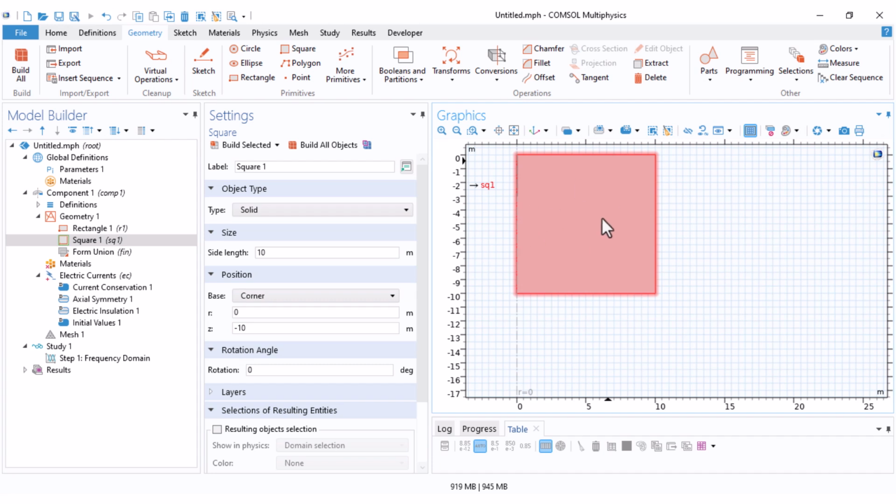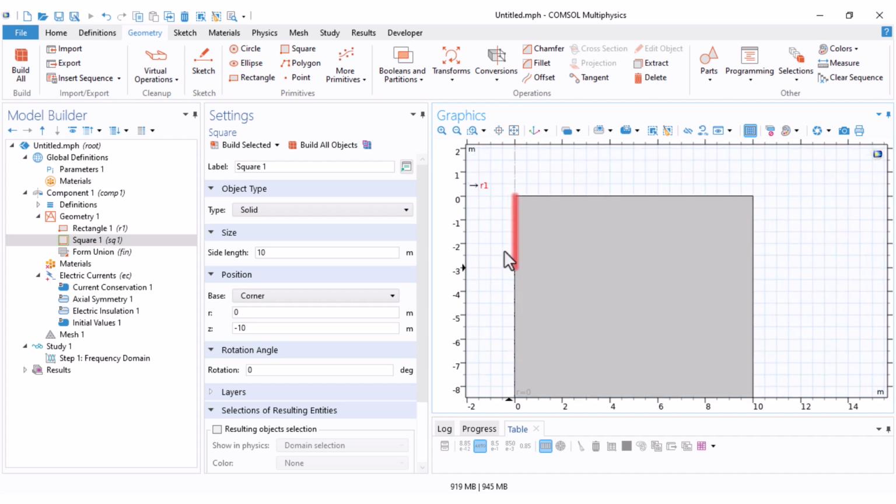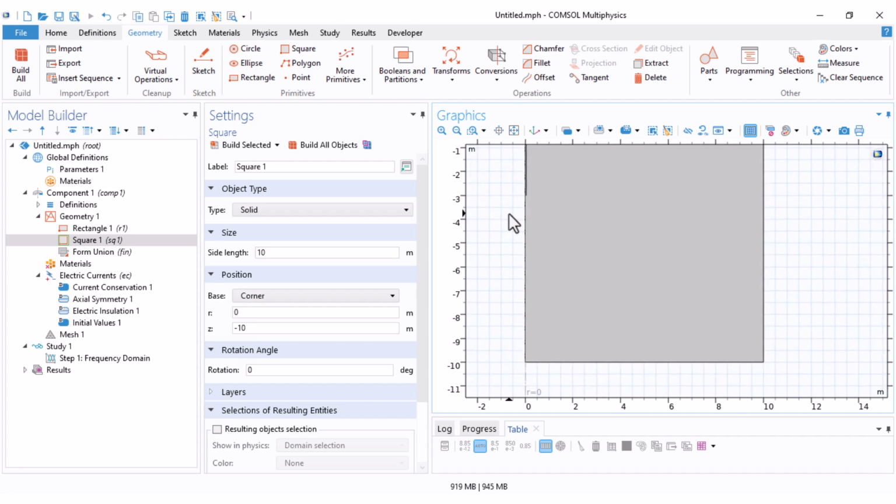We know from the theory that the measure of the voltage drop and the current density occurs within a limited space around any electrode system. Therefore, 3 or 4 times bigger ground, I think, is enough for the calculation to be valid and accurate. Our grounding system has a depth of 3 meter, 3.39 meter.